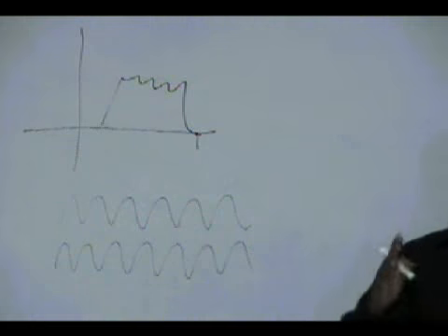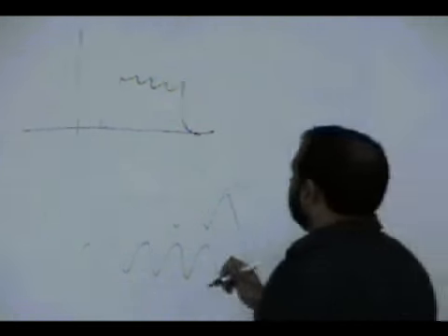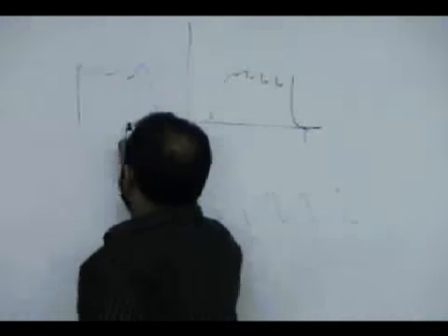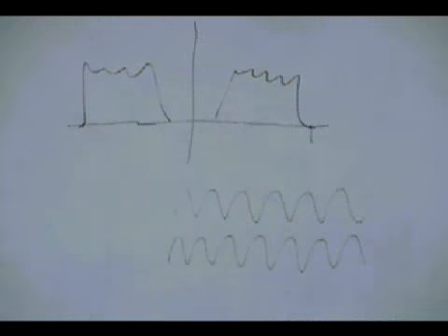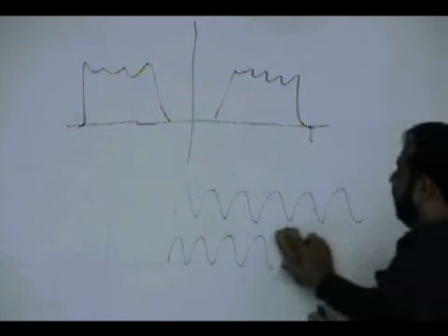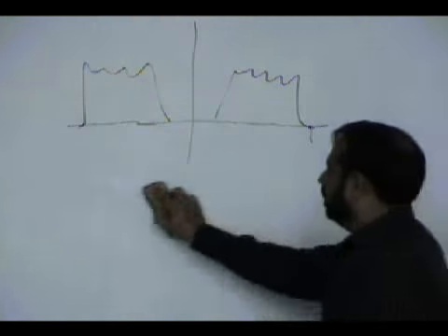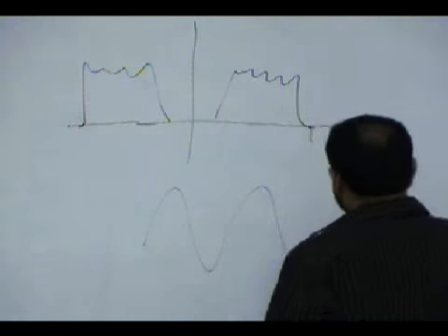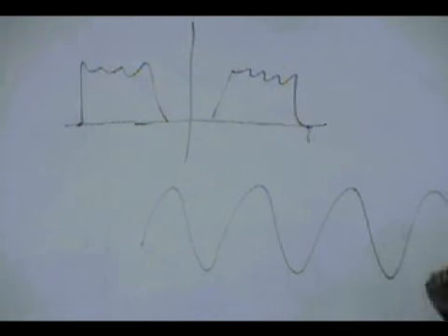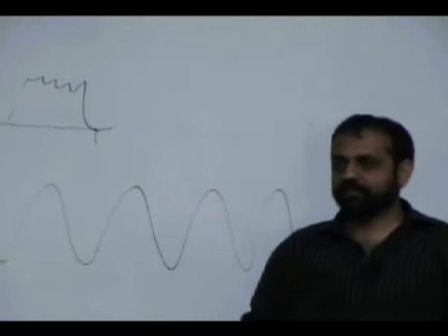If you see this spectrum on both sides, it means it is just a cosine, because remember, two exponentials here, exponential here and exponential here means a cosine. So usually for a real signal it is a cosine. So there will be a high frequency cosine. Okay, now here is a question. If you have a cosine, how many samples are required to capture this cosine?